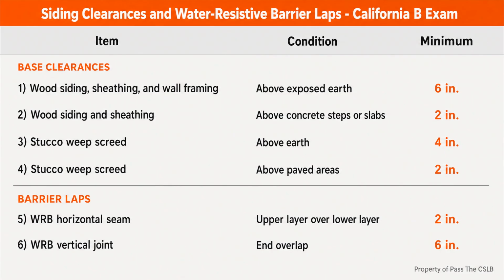Imagine a hypothetical project where the stucco crew leaves the correct clearance above rough grade. Later, landscaping raises the soil until it covers the screed. The original measurement may have been correct when it was documented, but the finished wall no longer has the required separation or an open drainage edge. The practical response is not to argue about which crew touched it last. The practical response is to restore the final condition before closeout.